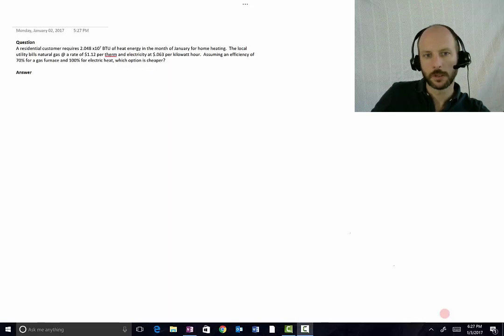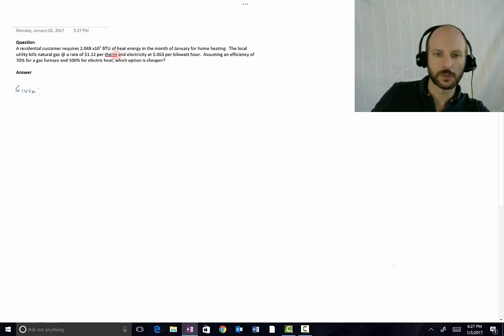So the question here is really asking you to compare the total amount of the two fuel sources used, electricity and natural gas. So again, I'm going to use the given, find, solution, answer method to analyze this problem. So we just want to go through the problem statement and extract the givens. So the first is what is that total energy in BTUs? We can see that number was 2.048 times 10 to the 7th BTU, or British thermal unit.